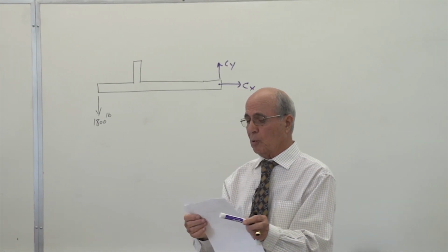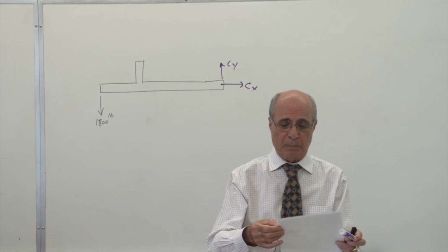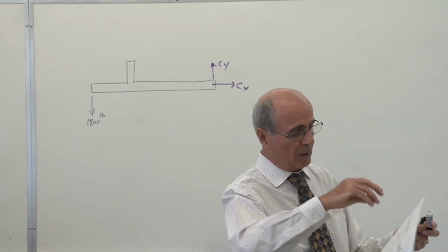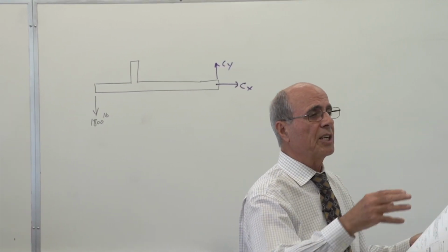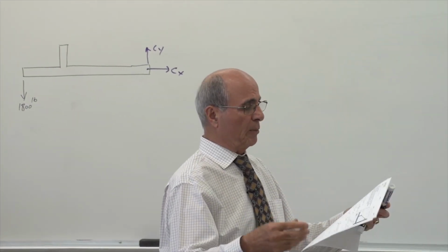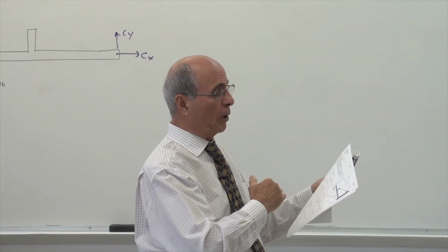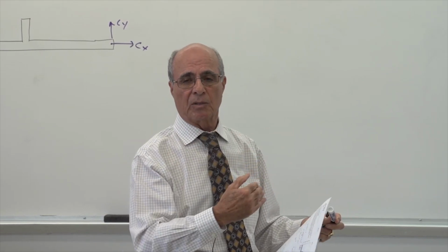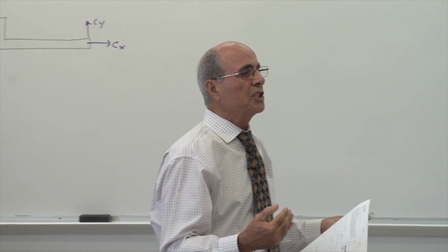And as you see, I call it rod BD. You can call it cable BD. I don't know the way the picture is. Sometimes we put a rod there, sometimes we put a cable there. As you see, it is a cable or it's a rod. But obviously, when you push down the blue part, that cable or that rod is going to be in extension, yes or no? So it's going to be in tension.